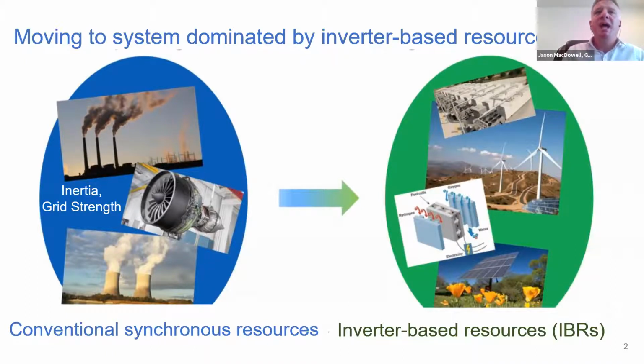They're directly coupled, and the stability and the power given to the grid to serve the demand, and all the behavior, is directly coupled based on the machine and the machine design, and it's more based on the physical attributes of that machine and how it interacts with the grid. And obviously there are controls like excitation to control voltage. We'll go over what that means, and other aspects of the synchronous machine like a governor to control speed and maintain frequency that is very important to the overall capability.